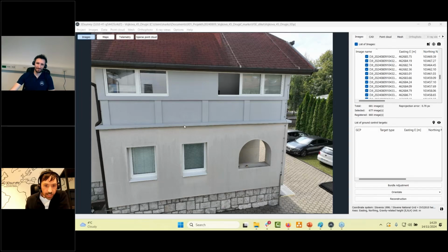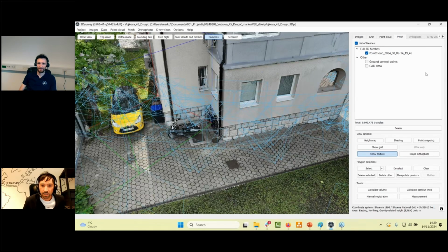First question is, what do you recommend for the number of triangles? Default is 2000. Okay, let me correct that, sorry, yes, default is 2 millions. Yes, that's true. So in most cases, 2 millions is good enough. You can go up to 10 millions easily. So as you can see, this mesh is calculated with 10 millions triangles.